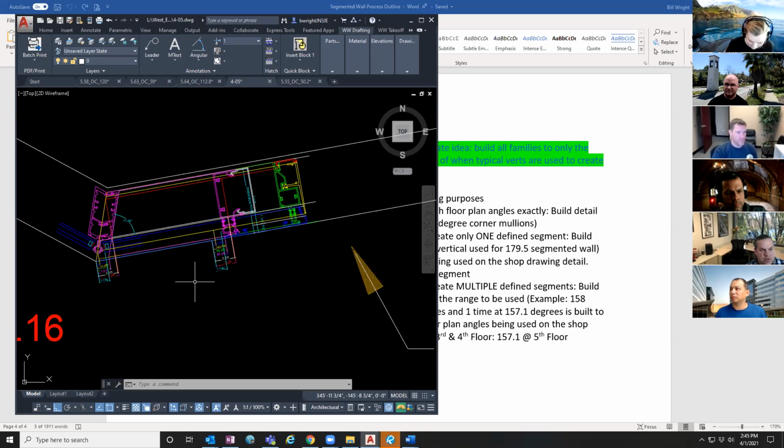And each one of those horizontals was being mitered to create this sort of truss system that goes across. And the person that was doing the fabs initially had laid out all of those miters to the first place after the decimal. And during this process, we came up with going 5 places past the decimal.